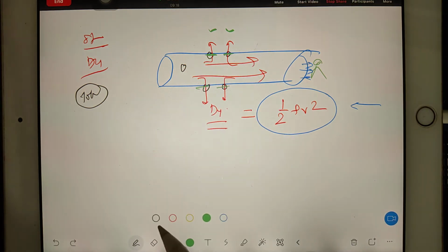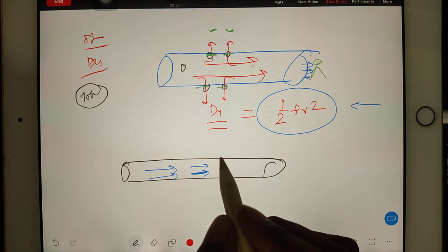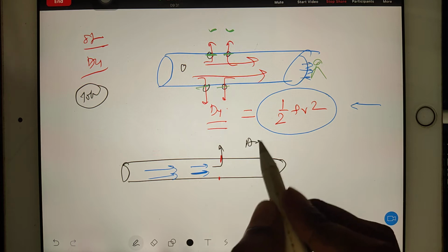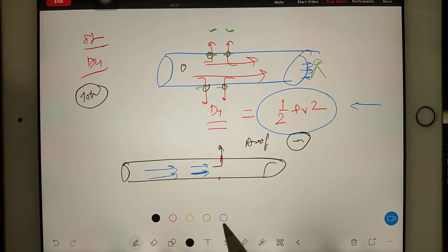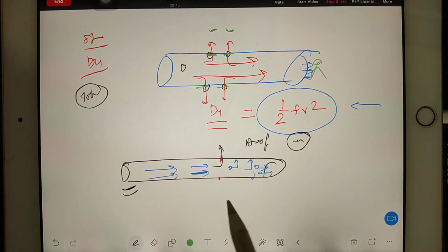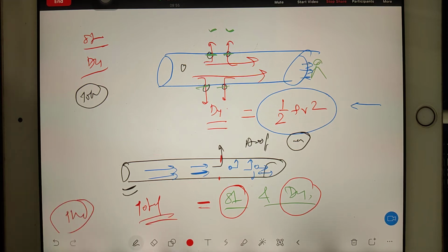But if you talk about real situations, whenever there is an oil flow or any liquid flow in the pipe, if you make a hole here, then definitely there will be leakage, which is proof that yes, there is static pressure present, because molecules were bombarding the wall and they were also going ahead. It means what? In all real life flows, you have static pressure also and dynamic pressure also. So the sum of static and dynamic pressure we say is total pressure in thermodynamics, right?